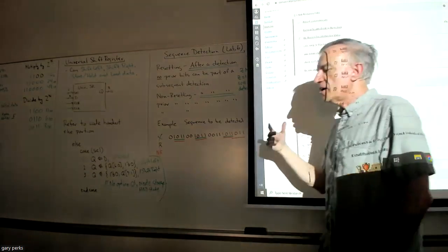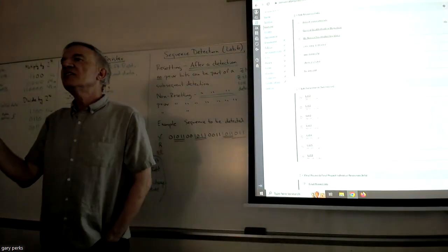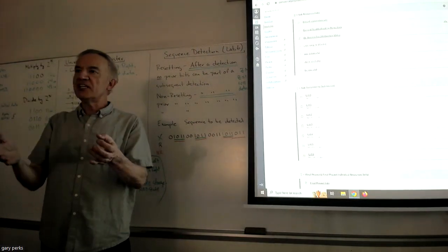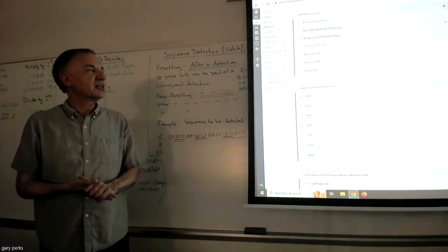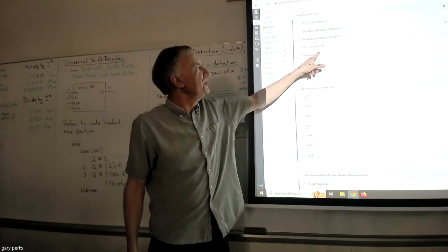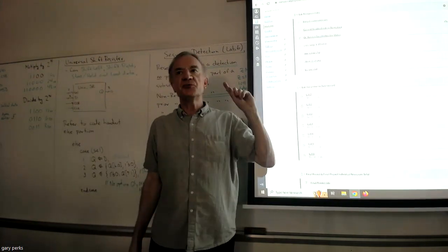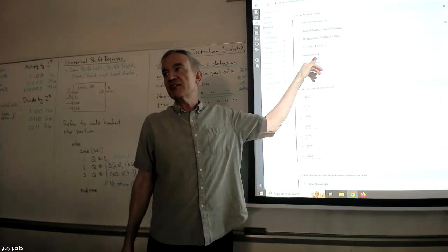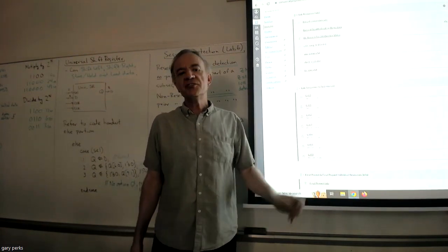And Vivado can run mixed languages. So you can have Verilog with SystemVerilog or SystemVerilog with VHDL, and it will all work. So you're just going to use these files as is, although there is one modification you'll have to make to the clock divider module. And what do clock dividers do?